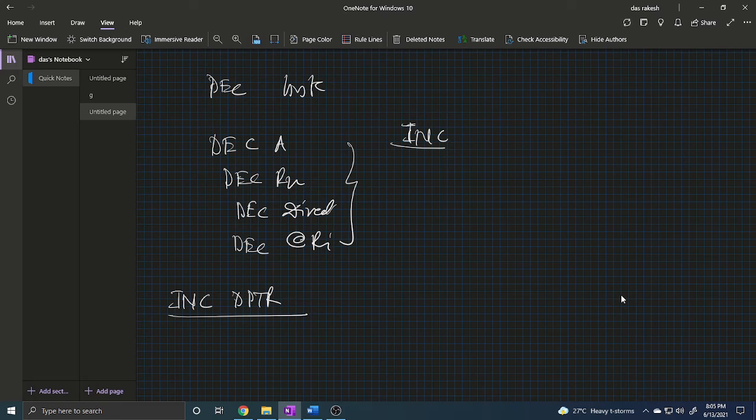So these are basically the multiplication and the other arithmetic operations in 8051 microcontrollers. And next is the divide operation in 8051. There is another instruction available which is known as DIV. So DIV AB means this instruction divides the byte in accumulator A by the byte in register B. It is assumed that both registers A and B contain an unsigned byte, and students please note down, after division the quotient will be in register A and the remainder is stored in register B. Please note that, it's very important.